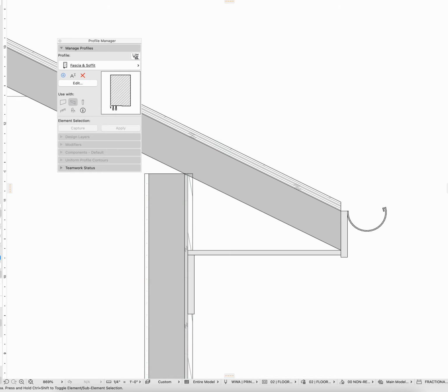let's get rid of these fills. Let's go back into here, grab all of this stuff. I'm actually going to paste it back in to include that hotspot. So the hotspot right there is where I want that reference line. So that's going to start right there at the 0, 0 point, and we'll say OK. And I want this to be applied to a beam, so I'll say save.